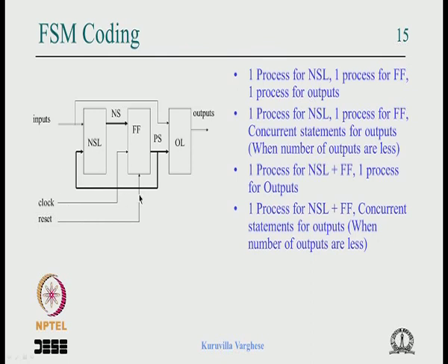We can also look at different scenarios with these logic blocks combined, and we will come to that. We also have to look at the reset. The reset can be asynchronous or synchronous. If the flip flop has an asynchronous reset, then we will use that, so asynchronous reset in the flip flop process. So wherever the flip flop is there, we will include the asynchronous reset. Or we can include a synchronous reset along with the next state logic.